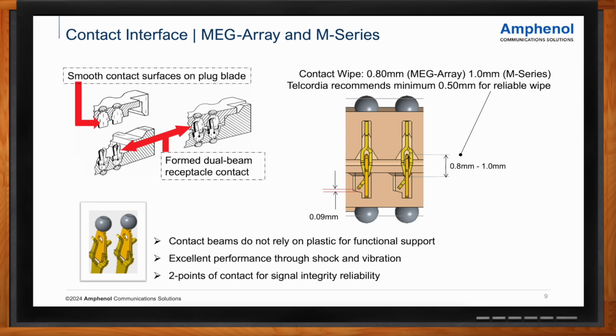You've got 2 points of contact, which the industry looks for. But with that offsetting normal force, if one contact would theoretically start to become less engaged, you're becoming more engaged on the mating half. And what that does for us is it makes this an ideal connector for those automotive applications where you certainly have shock and vibration, and even applications like solid state hard drives.